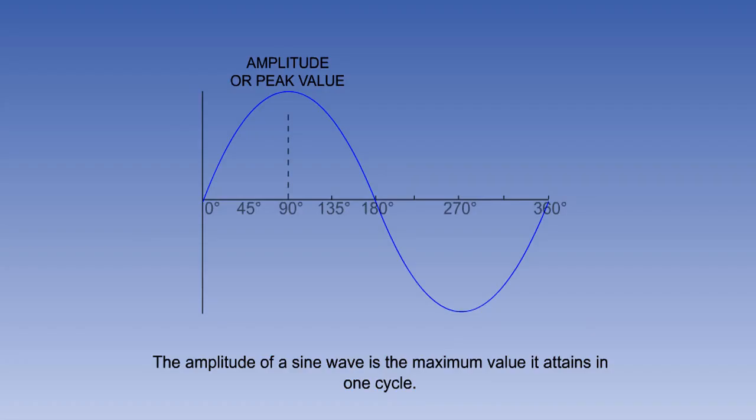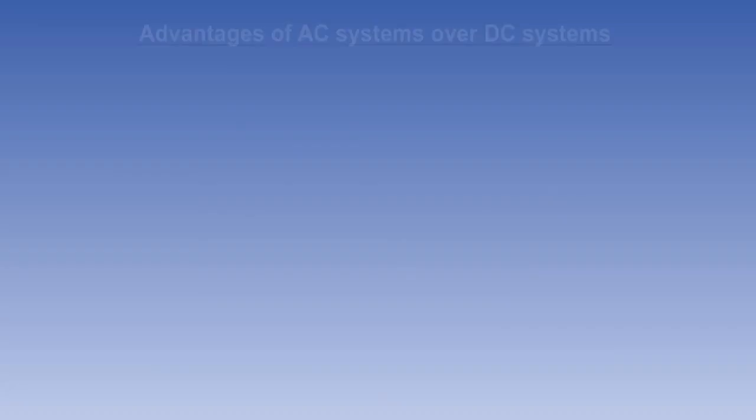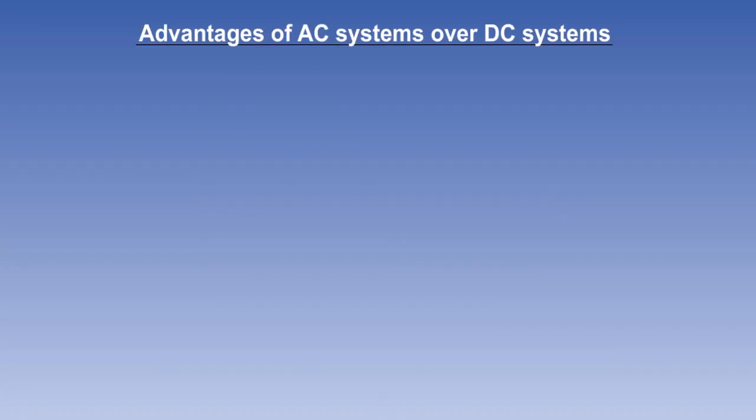Alternating current or AC electrical power has a number of advantages over direct current or DC. Some of these advantages are self-evident, but others will become clear as you move further. AC generators are simpler and more robust in construction than DC machines, because they do not have commutators, and only the light current field coil is rotating.